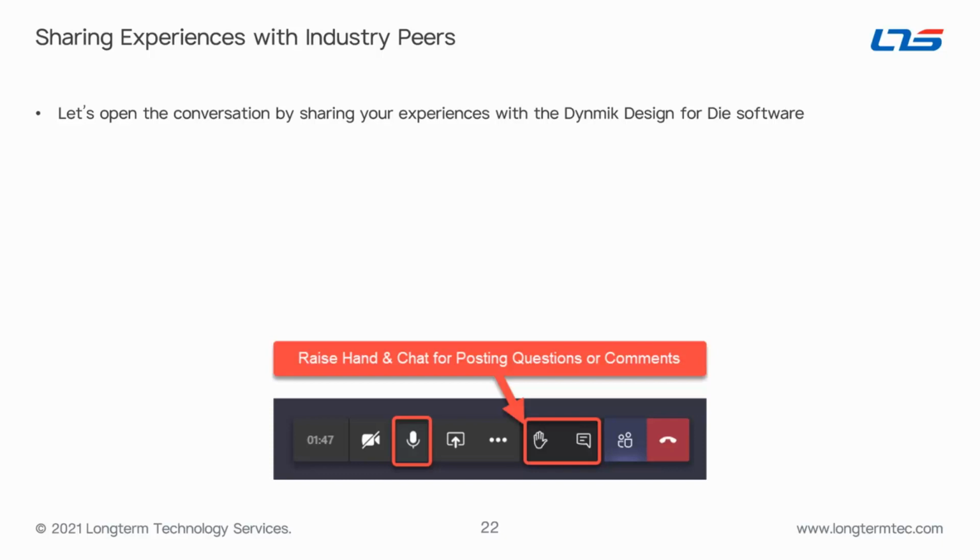What I found was that if you design your transfer up front, it's fairly fast to simulate it now with all the new tools that we have in there, and it's getting easier and easier to design your transfer before you design your die. Before, it used to take a long time to do stuff like this, and you'd have to wait till the die was designed and almost finished and almost built before you design the transfer.